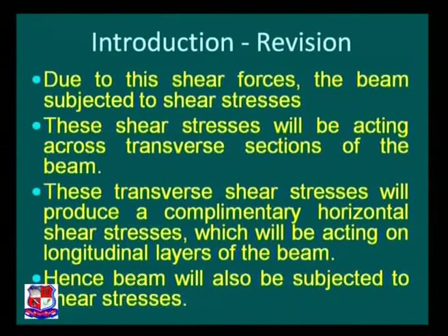This shear force leads to shear stresses. Hence these shear stresses will be acting across transverse sections of the beam. These transverse shear stresses will produce the complementary horizontal shear stresses which will be acting on longitudinal layers of the beam. Our intention is to study these shear stresses and their variation along the length of the beam, specifically along the transverse section.